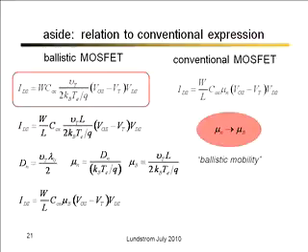In these small nano devices, there's a lot of scattering in the source. That's what maintains thermal equilibrium. Then the electrons go across the channel without scattering. Then there's a lot of scattering in the drain. That's what maintains equilibrium in the drain. The distance between scattering events is the distance between the source and the drain. So in this ballistic device, the distance between scattering events is the length of the channel. That's what's coming out here. So we could take the textbook diffusive expressions and just replace the real mobility by the ballistic mobility, and we would have the ballistic answer.